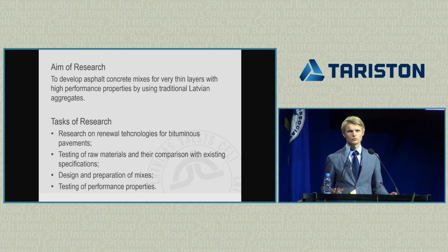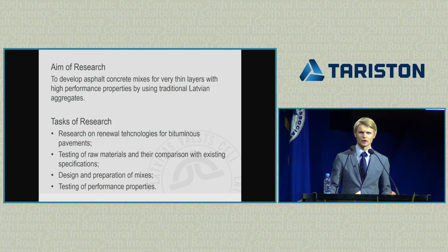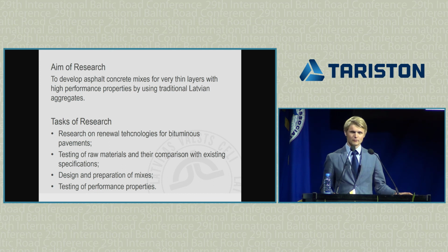The aim was to develop asphalt concrete mixes for very thin layers with high performance properties by using traditional Latvian aggregates. The main tasks were research on renewable technologies for bituminous pavements like slurry seal, chip seal, microsurfacing, and asphalt concrete for very thin layers, or in other words, BBTM.